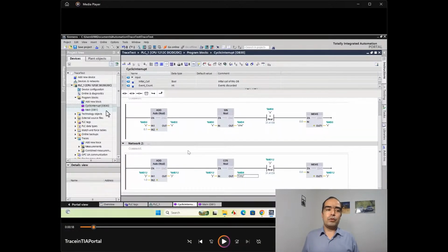Here is an important point: to take FFT in TIA Portal, we should know the signal's frequency. I wanted to take the FFT of my sine and cosine functions. FFT is an abbreviation of fast Fourier transform. So to perform a Fourier transform, the sampling rate must be specified. Otherwise, TIA Portal won't be able to take FFT from your signals.